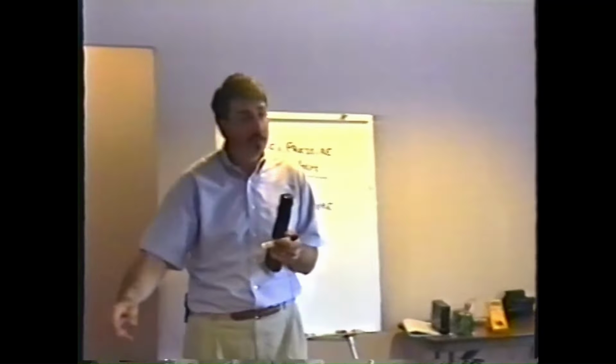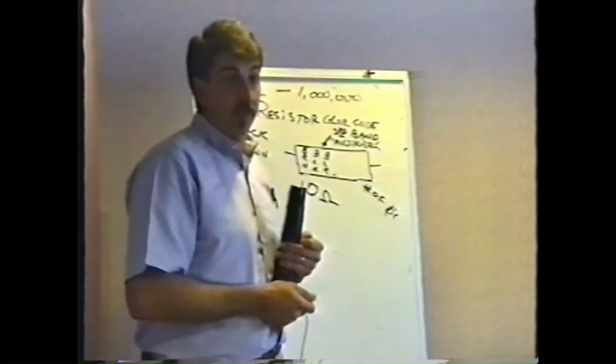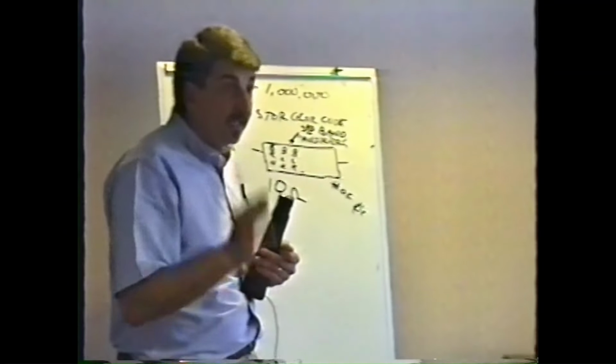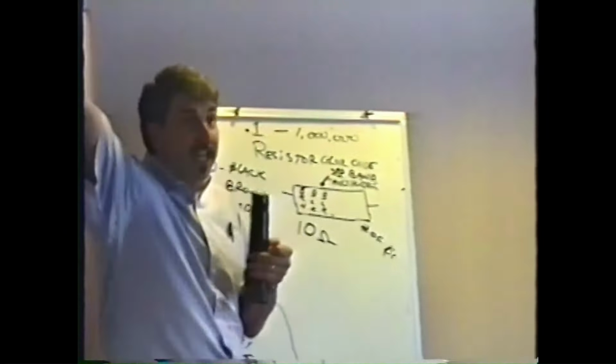And they see this resistor, and for some reason they want to check it. So they put their meter on ohms. This we'll do in just a little bit. They put their meter leads across the resistor, and the meter doesn't read 100 ohms. It only reads 10 ohms, which is what it really is, right? They go, oh, I'm a genius. I found it. This resistor's partially shorted.